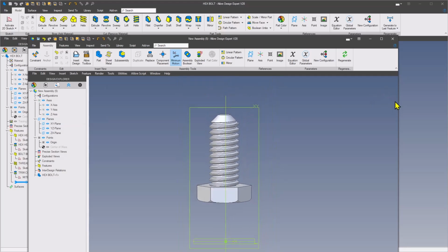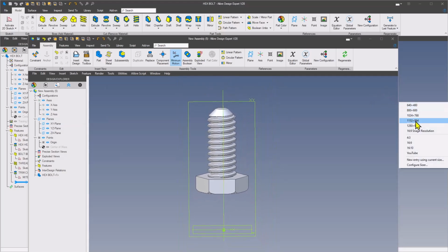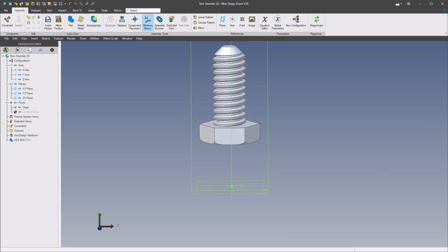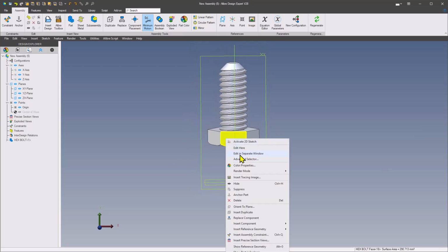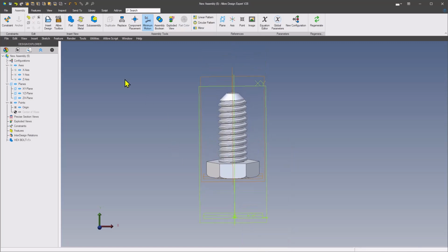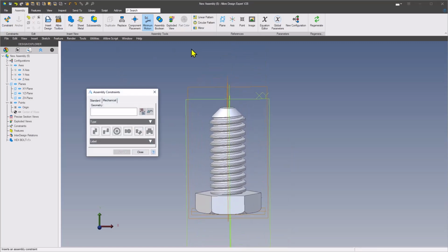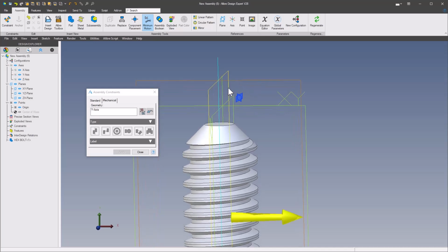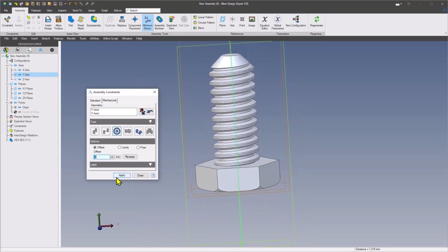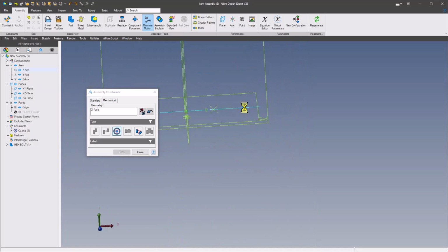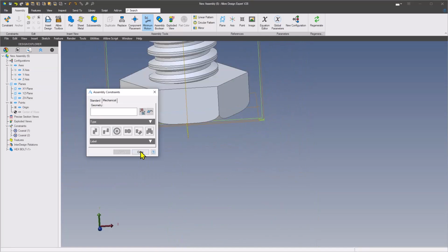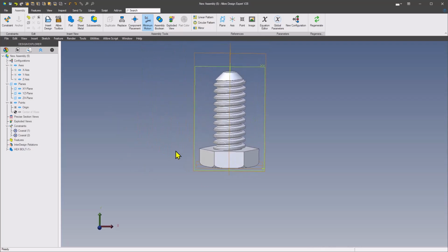it, and then let me resize my window here. Okay, and now I've got my bolt assembly. Let me show my reference geometry and constrain that to the origin. And I'll grab my y-axis and my x-axis and apply that. So now this is locked at the origin.